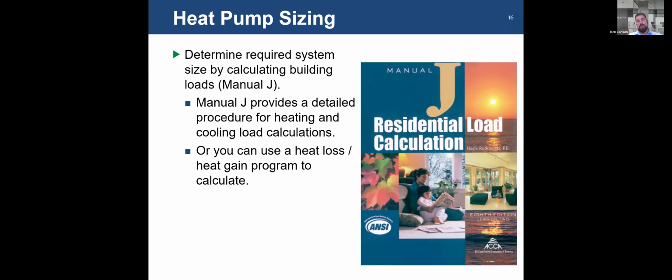That causes a lot of oversizing. A lot of times, to make more money on a larger piece of equipment, there might be some small instances there, but I think most of the oversizing that's done in the industry is because it's been replaced like in kind, and nobody did a Manual J to figure out exactly what was required, or they're using old school rules of thumb. And don't get me wrong, I've done this for back of the napkin math.